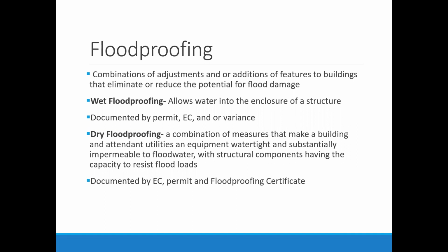Whereas dry floodproofing, which is only for non-residential structures, is a combination of measures that make the building and utilities watertight and substantially impermeable to floodwater. And so it has these structural components with the capacity to resist flood loads. This is a large engineering project that we don't even have any examples that I can think of in Kansas, but I just wanted to make it clear about the requirements for dry floodproofing